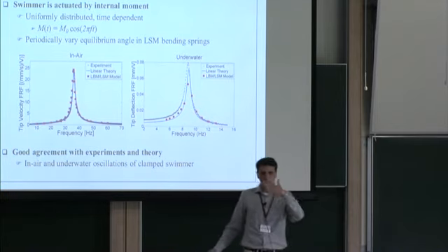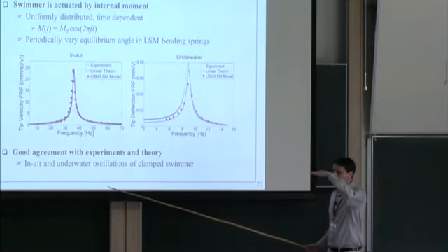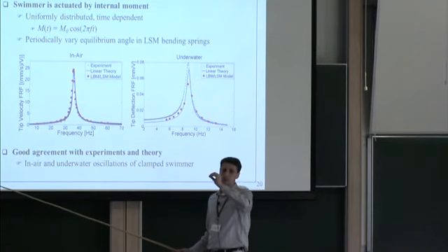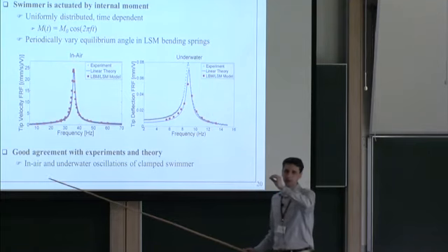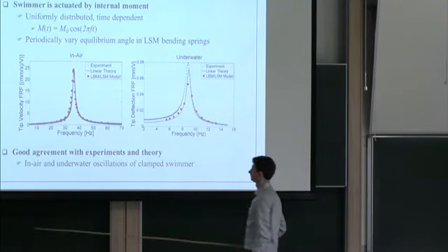So to keep it swimming, we also fix the angle at the root of the swimmer, so it can move horizontally, but there's a clamp condition at the root of the swimmer, because if we don't do this, everything will be symmetrical and will just stay in place.